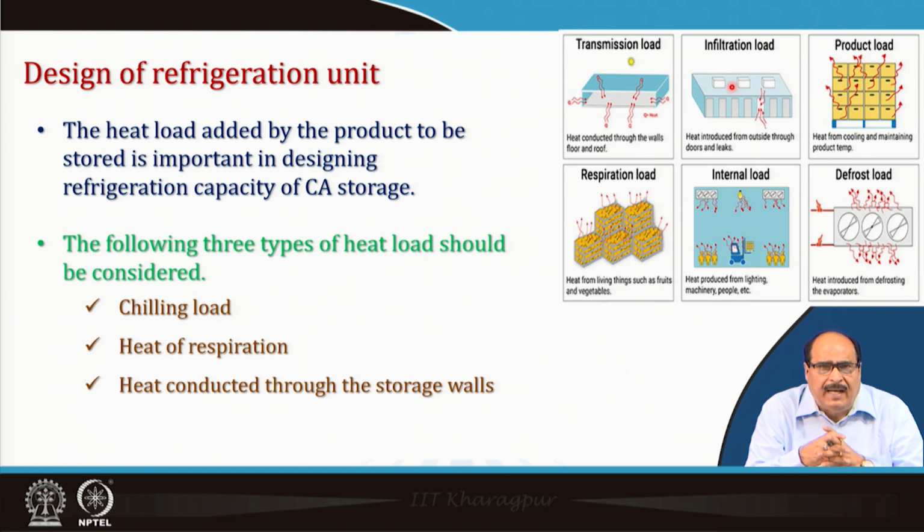Then let us discuss the design of a refrigeration unit. The heat load added by the product to be stored in the unit is important in deciding the refrigeration capacity of a CA storage unit. There are various types of load like transmission load, infiltration load, product load, respiration load, internal load or defrost load, etc. But three major loads which are considered in designing the refrigeration unit include chilling load, heat of respiration and heat conducted through the storage unit.